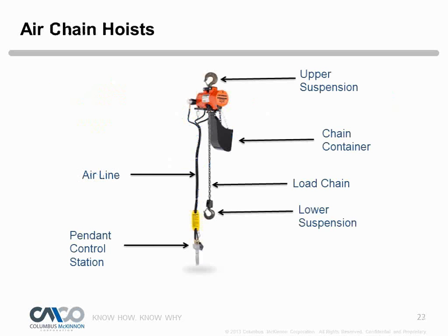And there, quickly, the Xtra Load air hoist. It pretty much looks like an electrical hoist. In some of our electrical hoists, we do convert to air hoist, so they would look almost the same, except there's an air motor at the end. So we have air supply lines, but it is a chain hoist, and it has its unique applications. The nice thing about air is we can get a lot faster speed. Some would go up to 65 feet per minute, so some extremely long, fast speeds.